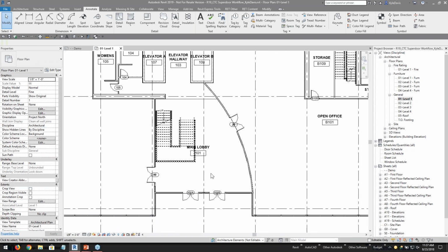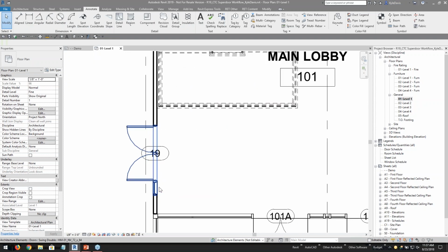And the same procedure would be for Windows. If you are using Windows within a Revit project, we do have in our tool currently the frame as part of the window category. So if I was to tag Windows, that frame would show up as well as a tag. So if you want to avoid that, again, do the select feature for Windows, or if you did the Windows feature, it would tag that.